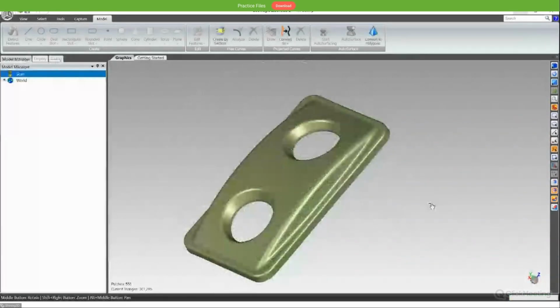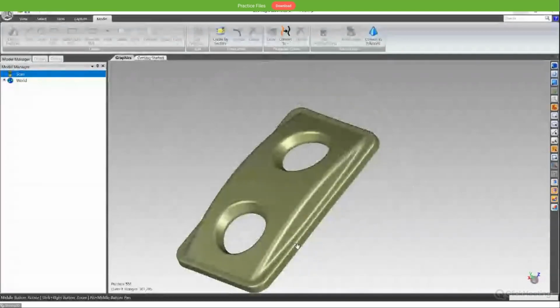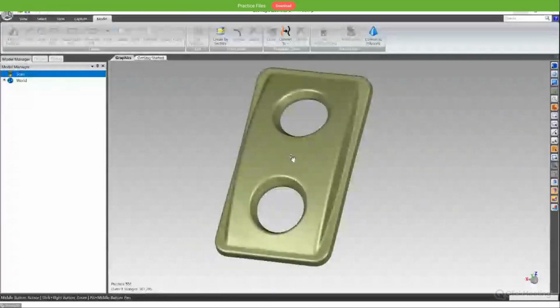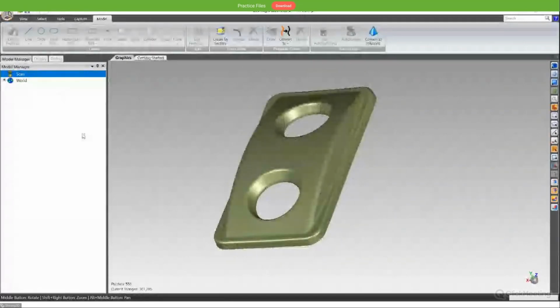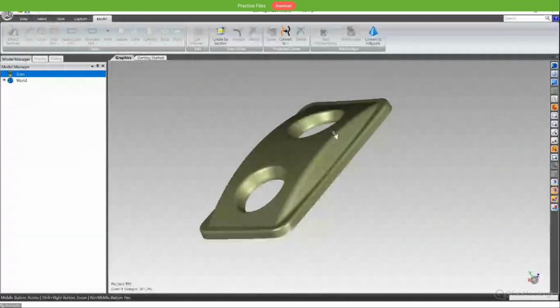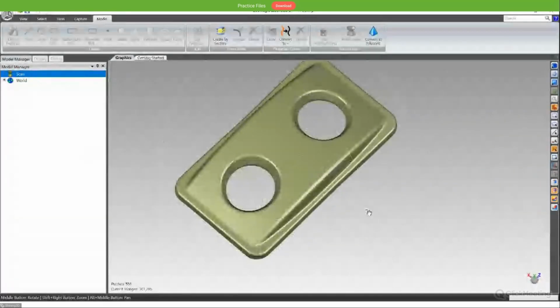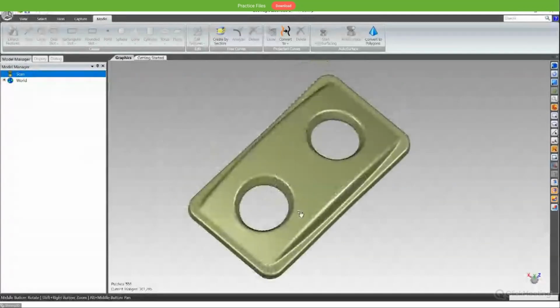Here we are not able to see the patches, right? But after you do the auto surface, you can export it as an IGS file, and if you open it with a CAD software, you will see the edges of the patches. To check the patches in Geomagic Essentials, you click convert to polygon, choose convert to curves and click OK.